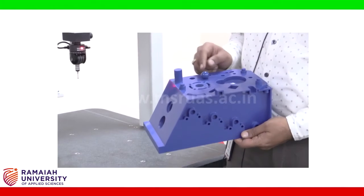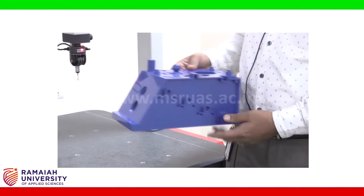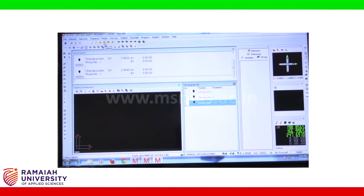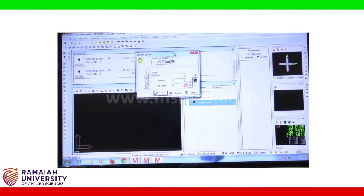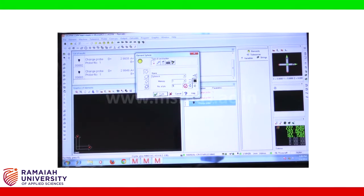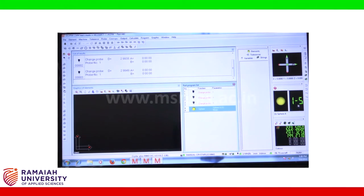As a beginning, let us measure the diameter of this sphere. The sphere. So I am mounting the component on the surface plate. Now I am choosing the sphere option, and you can see the sphere. The name of the sphere, let us call it sphere A, and we are using 5 points to measure the sphere, and these are the different options. Let us keep it to the default options and start measuring the sphere. So you can see here the CMM is waiting for the first point. So I am going to do a first point contact.